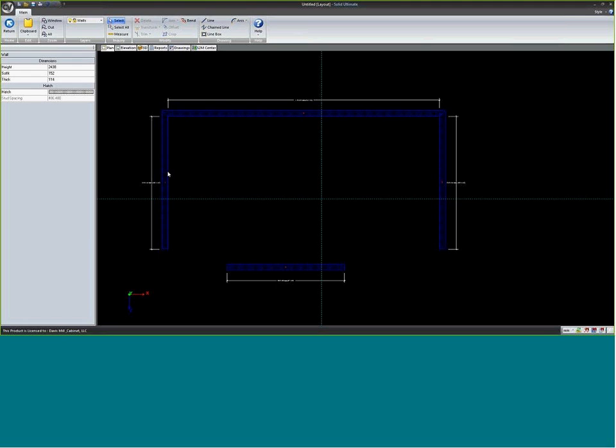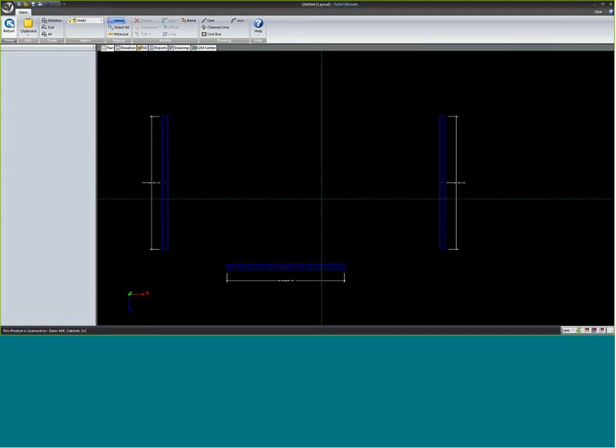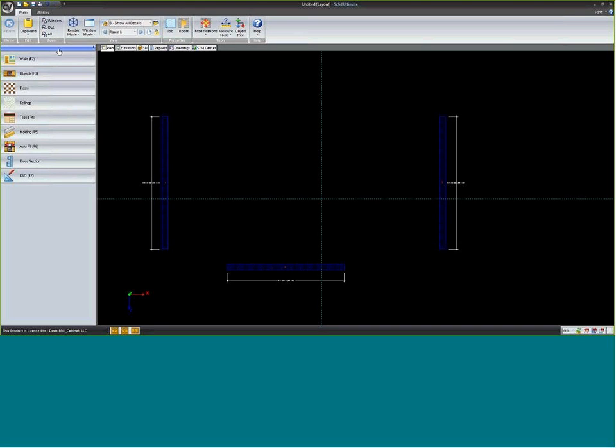I'll cover resizing and things here in a minute, but what I want you to watch is, in wall mode, if I'm on the select tool, I can pick any wall drawing and delete or move or change its size. Once I escape back to the main room, the standard tool set, if I click or draw a box around these walls, it doesn't pick anything. It doesn't know I'm trying to pick walls. If there were cabinets on the walls, it would be selecting cabinets.